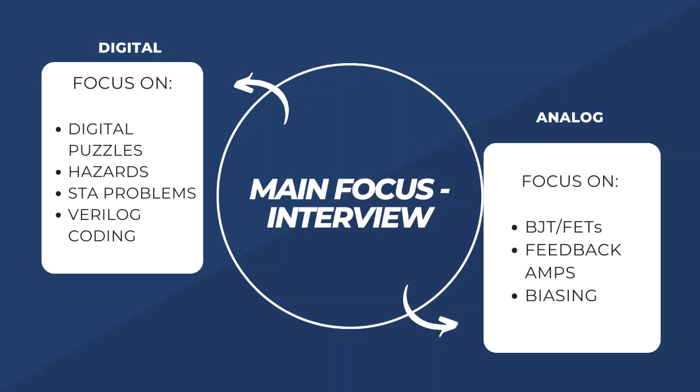The next one was the STA problems. So the MCQ had a lot of numericals from static timing analysis, but the interview had more of an application-based question. So we had questions like, if one flip flop of the system is in one part of the chip and the second one is far away, what are the phenomena that you can experience? And as you answer, hold violation, setup violation, they tend to build up on the question and ask you how you can solve it, what problems you will encounter when you solve it, and so on and so forth. So that was quite difficult.